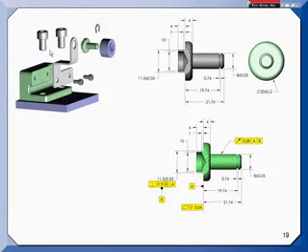Now, if the design changed, let's say I had a casting coming up here and got rid of these two parts and just had a casting, and I was going to press this pin down into a hole in the casting. So I had this nice machined hole, and I was doing a light press of the stud in there, so I'd make this longer. Then things would switch around, wouldn't they? This diameter would become my primary datum feature, and then I would only hit one high point on the shoulder when I pressed it into place.